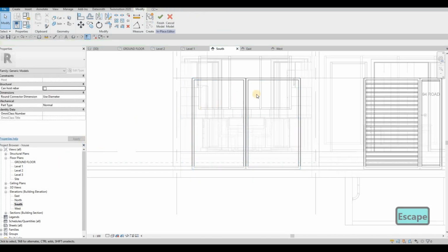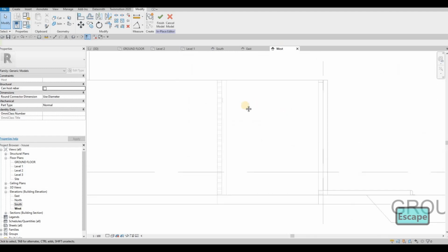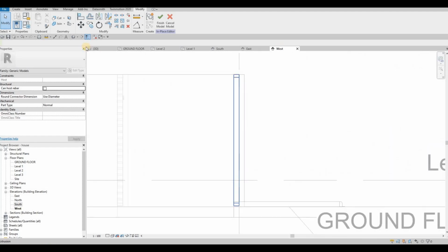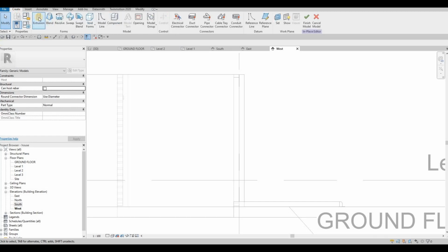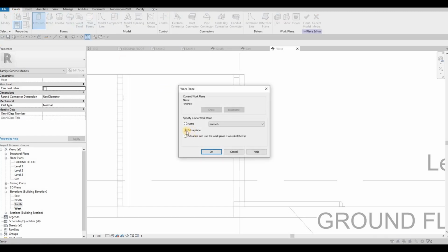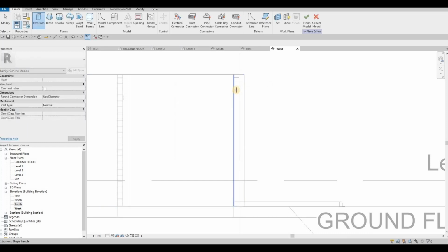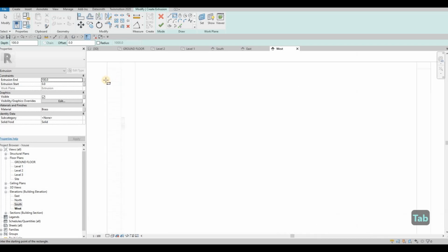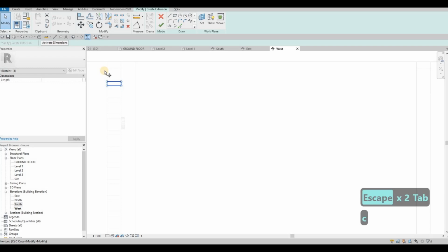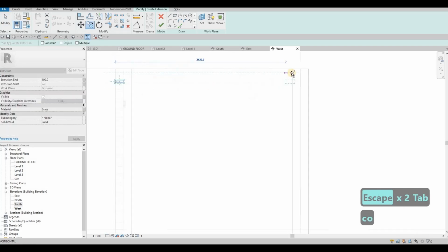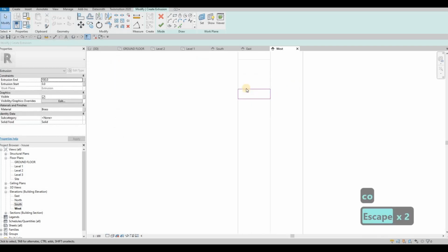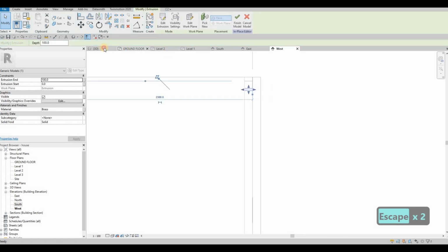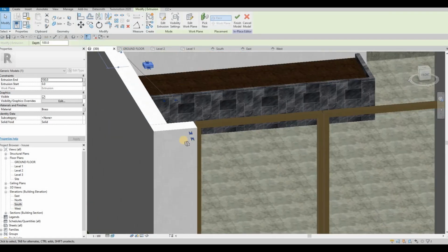And then after that, let's go to west elevation again. We can see it right here. We have the 20 right there, so we need to create the same thing. Extrusion, pick a plane. We're gonna select this plane right here, and then we're gonna copy this, copy it to there. That's perfect. Click finish. Go to 3D first to fix everything.